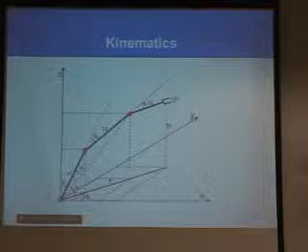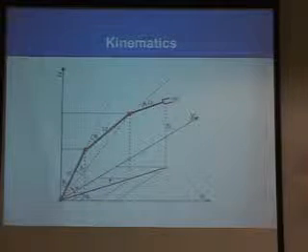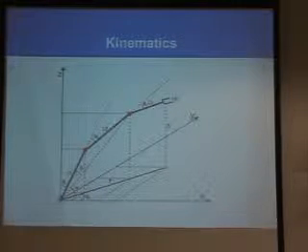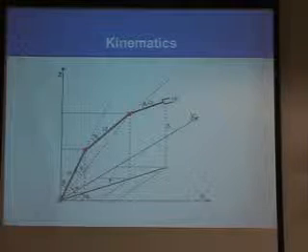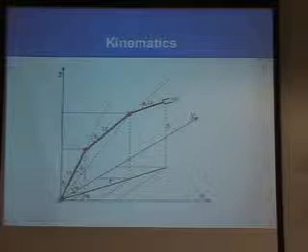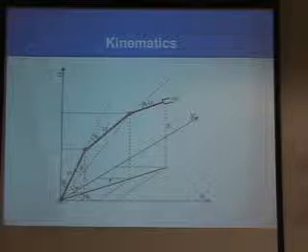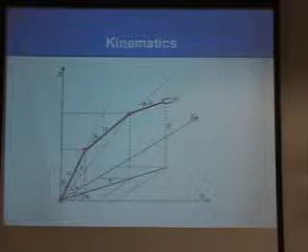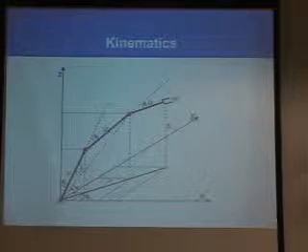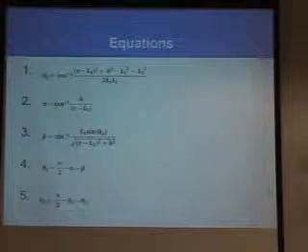So this is our kinematics model. We have 3 links and 3 angles. And we simplified it by setting the last link to be always horizontal, so it's not over-actuated, and we have exactly 2 unknowns and 2 equations. These are the equations that we get.